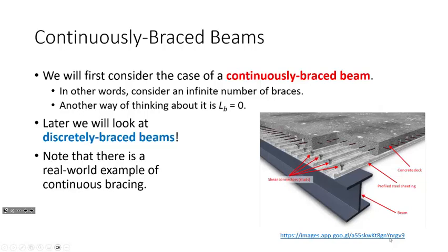I'm just curious. If you were on a DOH bridge site, probably the first thing you were thinking is, there are a boatload more studs than that on the beam, am I right? In bridges, we use a lot more studs than we use in buildings because bridges are subjected to fatigue. They have loads on and off, etc. So you need more studs in bridge design than you do in building design, where we're not worried about cyclic loading to that scale, if that makes any sense.